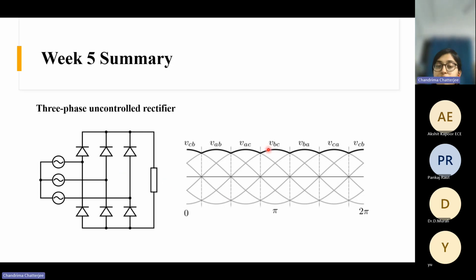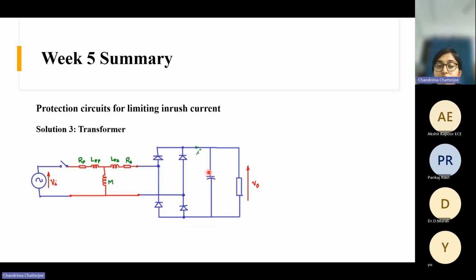The operating principle is the same as the single phase rectifier. There is no difference, just that you have 3 legs instead of 2 legs. And here the voltage fluctuation is lesser than the single phase one. In the single phase one, in the absence of filter, we saw the voltage has a sinusoidal shape, and it reaches zero at each half cycle, right?